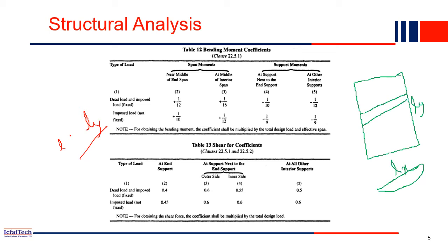So in the slab design, we'll consider a beam strip-wise. This is a beam we can consider while designing a slab, but the width of the beam is per meter, meaning 1 meter. This one-way slab we'll be designing as a beam. The only consideration is that the width of the beam will be taken as 1 meter. Whatever reinforcement is required in this strip of beam will be found, and that is for the 1 meter width.